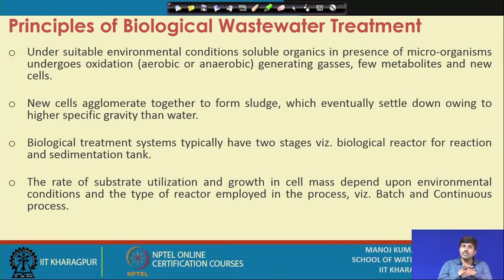Now, these new cells which are created agglomerate together to form sludge, which eventually settles down owing to higher specific gravity than the water. Microorganisms, and particularly the sludge, which is a combined floc of microorganisms, have higher specific gravity, and that is why they can settle down in the water. But they typically need a static or very low flow condition to settle down, as we were discussing in